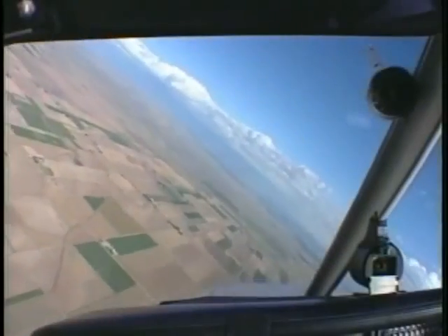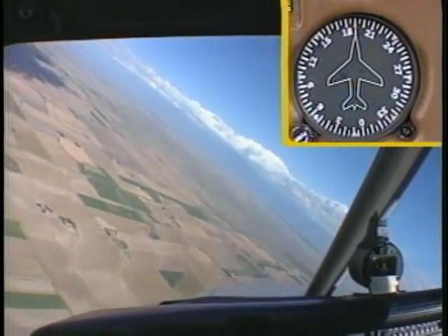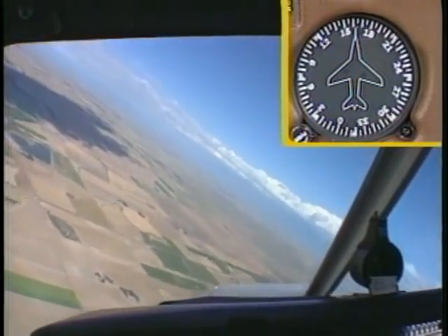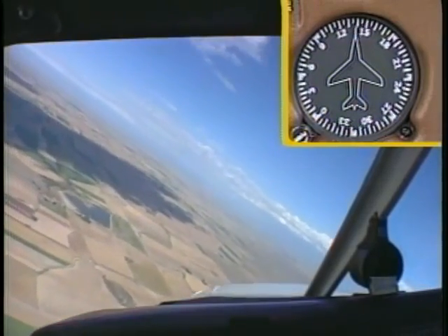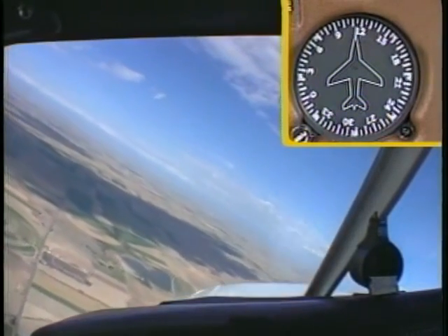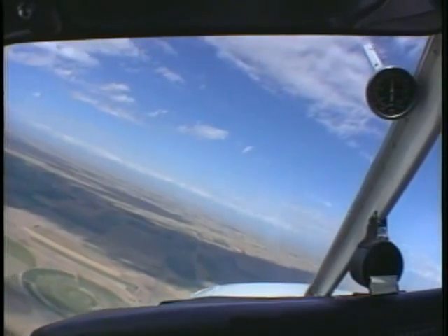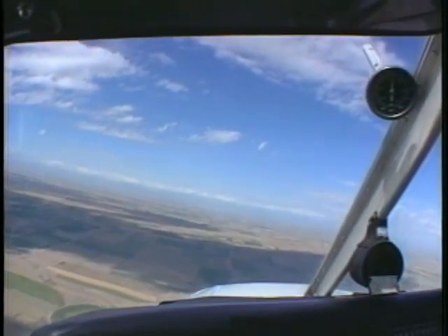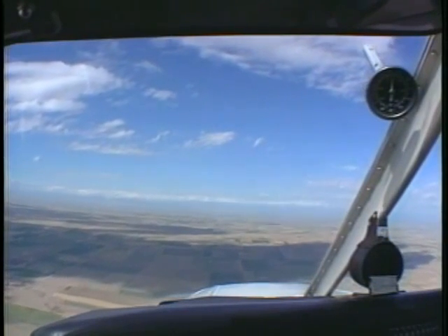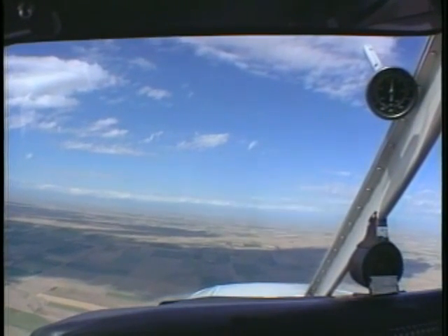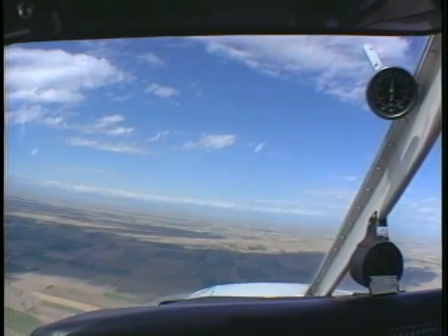To recover from a steep spiral, use your heading indicator and the standard 1/2 of the bank angle, along with your chosen landmark to determine when to begin a smooth rollout. As you level the wings, smoothly adjust pitch to maintain your airspeed and continue a glide on the recovery heading. During practice, be careful not to descend below a safe altitude.